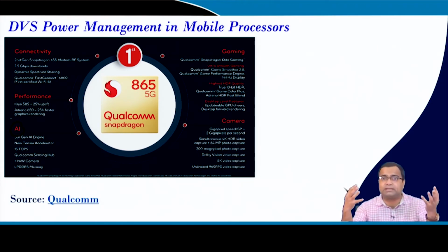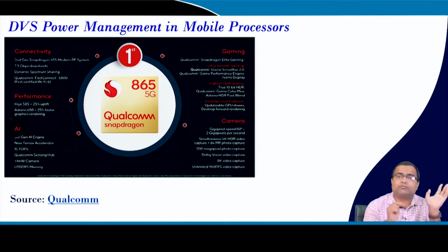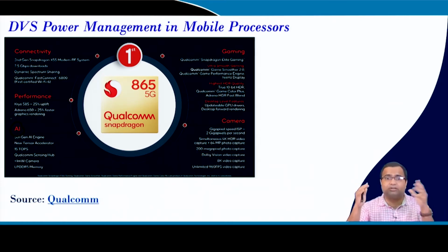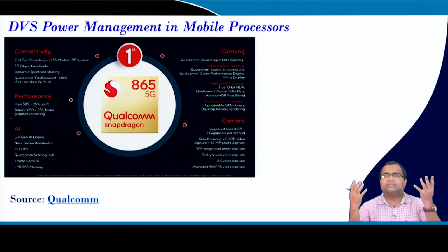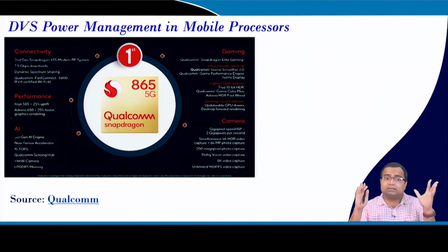But suppose there is some activity, then the camera will slowly start activating its processing feature and storing feature, but not to the full extent. As long as it identifies that something goes wrong, then it has to come to full-fledged operation, and we require the maximum computation, and there the voltage requirement will be different. So, this performance requirement applies when we talk about a smart camera, a smartphone, or 5G communication, because even for communication we may not need the same voltage level when there is no communication, or only very little communication, like just surfing the internet, where the data and speed requirements are different. But if we are watching a movie or playing an online game, then the supply requirement will be different.